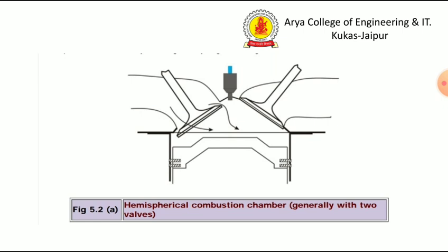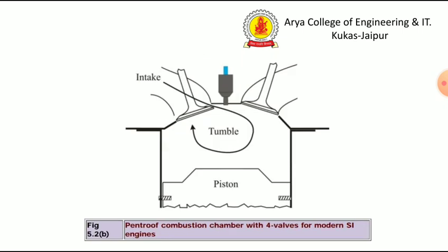Small cylinders have a smaller amount of burnt gases that form the high temperature adiabatic core. More heat transfer takes place from the burnt gases, as the walls are nearer to the bulk gases, and it results in lower NOx.